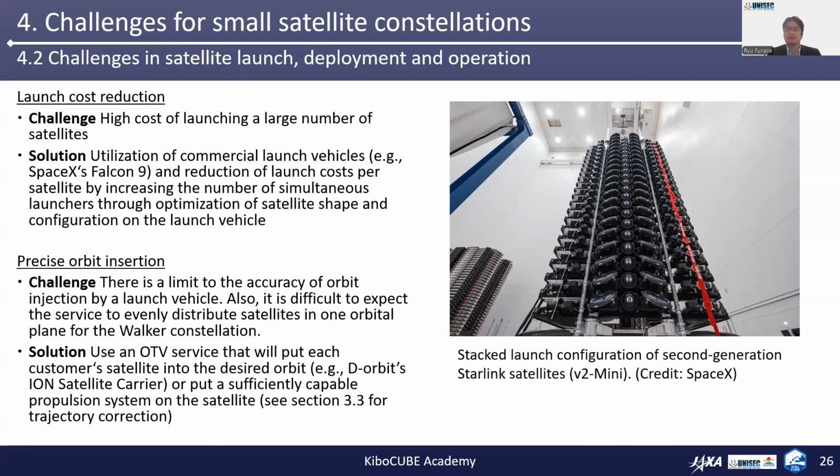For example, Starlink of SpaceX is designed to be flat, as shown in the right figure, and the number of satellites per launch is maximized by stacking satellites to make maximum use of the fairing volume. Another issue is the importance of accurate orbit injection for constellation satellite deployment. However, there is a limit to the accuracy of orbit insertion by the launch vehicle.